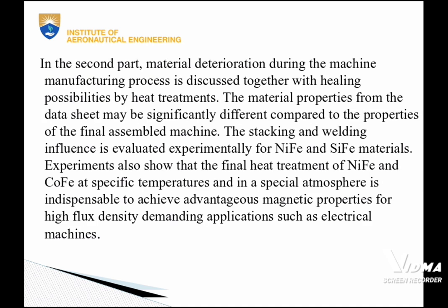In the second part, material deterioration during the machine manufacturing process is discussed together with healing possibilities by heat treatments. The material properties from the data sheet can be significantly different compared to the properties of the final assembled machines. The stacking and welding influence is evaluated experimentally for NiFe and SiFe materials.